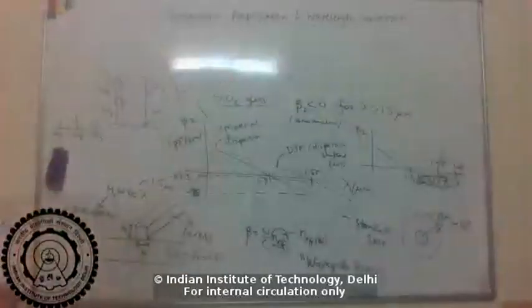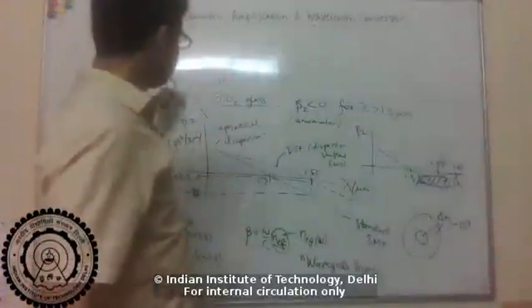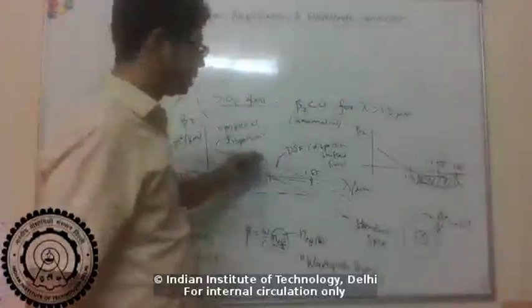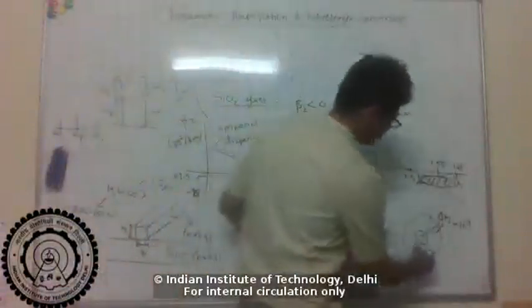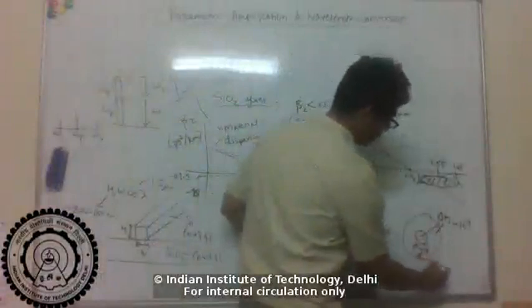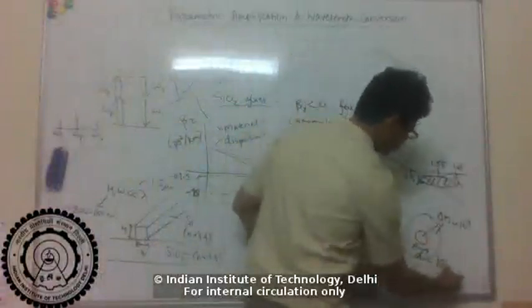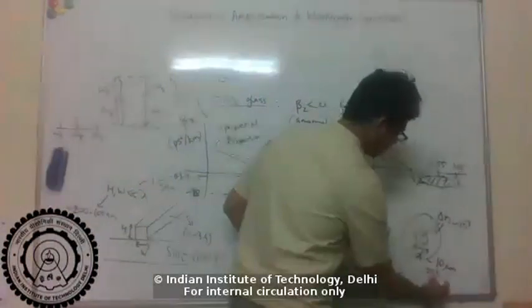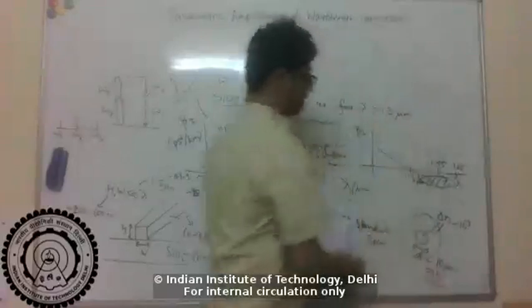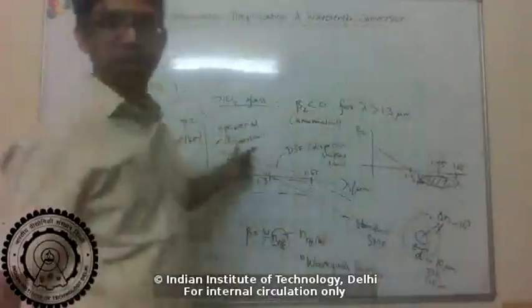Yeah. So the dispersion that you get just from the material refractive index, that's called material dispersion. And for optical fibers, basically the dispersion is mostly the material dispersion, right? Because if you look at the core diameter for single mode fiber, that's about 10 micron, which is much larger than the wavelength, which is 1.5 micron. So the waveguide dispersion is very small. Mostly the dispersion is due to the material itself.